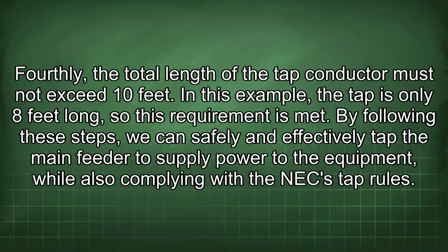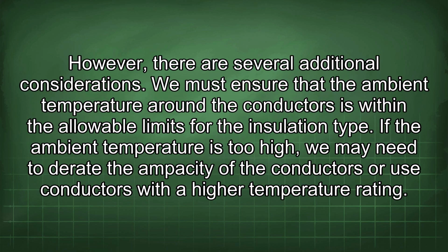In this example, the tap is only 8 feet long, so this requirement is met. By following these steps, we can safely and effectively tap the main feeder to supply power to the equipment, while also complying with the NEC tap rules. However, there are several additional considerations.